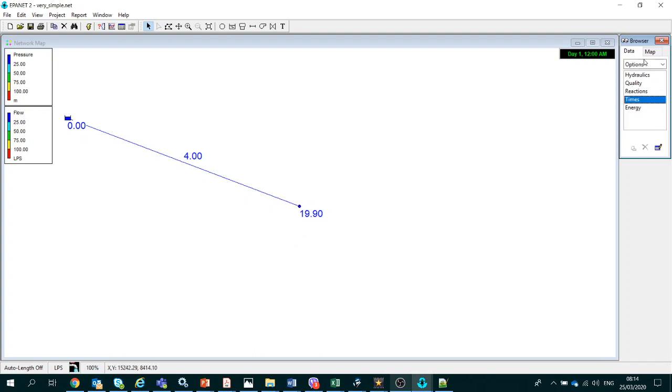So what will happen is then your pressure here will become negative. You can see this because this happens at 6 o'clock, they said. So go to 6, you can see there is a negative pressure. So this is an unrealistic situation. A network will not work like that, but the software will show it like that because the software assumes that the demand can be delivered.